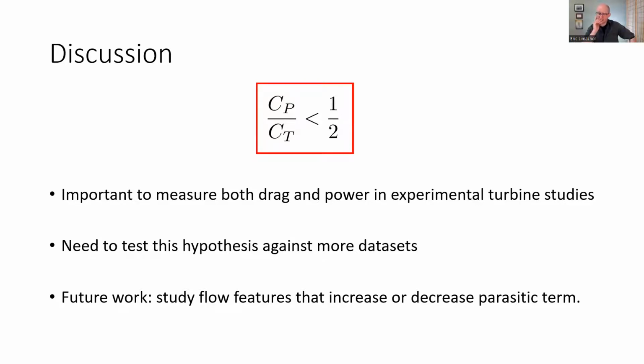I think because the two derivation paths follow very different logics, essentially, the different model of the flow. One is considering pressure and velocity, the other is making assumptions about vorticity. I think one really interesting point to point out is that in an actuator disk model, we are modeling the extraction of useful energy as a sudden static pressure drop. And so we're modeling the extraction of useful work without any associated vorticity generation. So through the lens of this work, that could be part of why it is able to predict higher power for a given thrust, because implicitly it's assuming something that's just physically not possible. If we're generating some power, we're going to generate some vorticity as well.